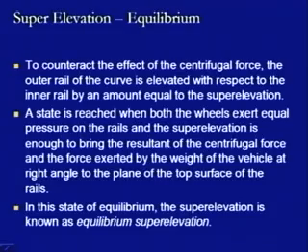So, this is a condition that we are trying to achieve, a state in which the resultant of the centrifugal force, which is acting in the outward direction, and the vertical downward force, that is the load which is acting downwards, if we take the resultant of these two, it tries to remain within the area of the wheel sections, and if it remains in that area, then the chances of overturning etc. will be omitted.